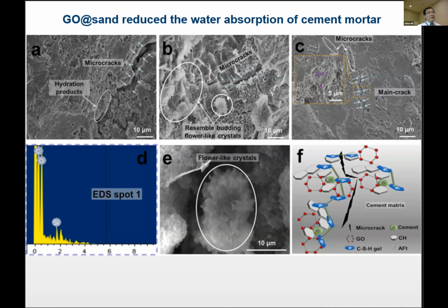Again, this is really fine. I was talking about this piece of paper, zoom in 1,000,000 times. That's where we're looking at this stuff. So you can see in general, you are seeing different patterns. Figure C is what we see as the graphene oxide at the sand. Figure B is the direct mix. They definitely look different on the microscope. You are seeing denser microstructure, narrower cracks.